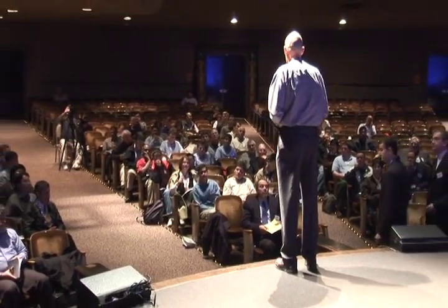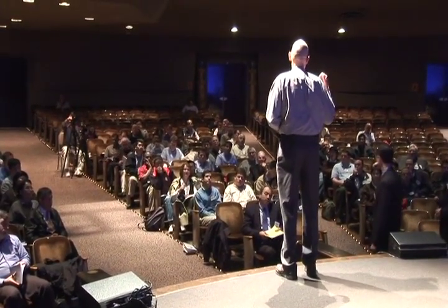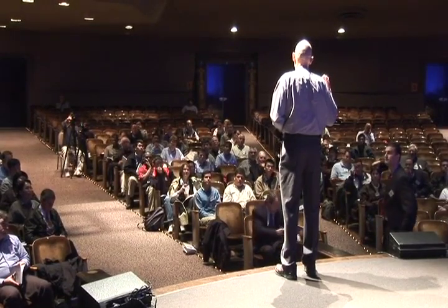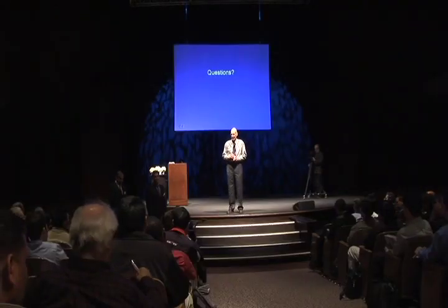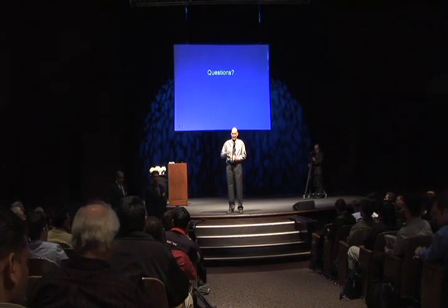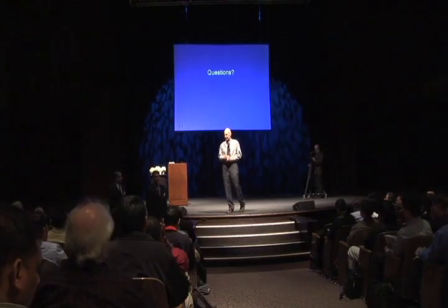I think what you may be getting at is that I showed the hysteresis loop for a buckling restrained brace, which increases in strength. And I think that a shear link may do the same thing. The shear hinge that we have doesn't do that right now. It does not give you hardening under progressive cyclic loading. It's on the list of things to do.